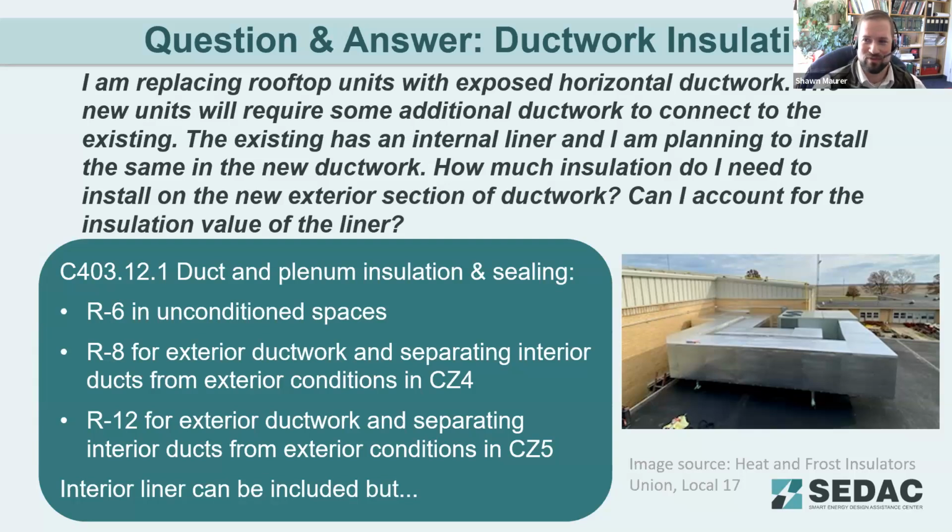If it's an unconditioned space, the code doesn't allow you to add in a permanently installed conditioning system. If it is a conditioned space, you could add that system in, but there are some other requirements if it's an unconditioned space already. So if you add the fireplace, now you also have to insulate the envelope. If that's not part of your project, then adding the fireplace isn't going to be allowed. So hopefully that answers a lot of the questions that came in with that one.